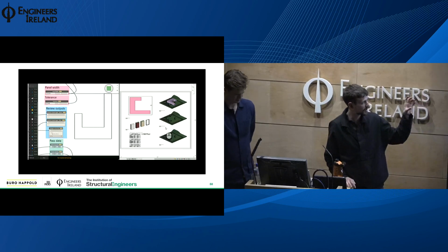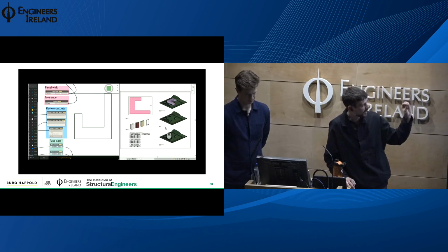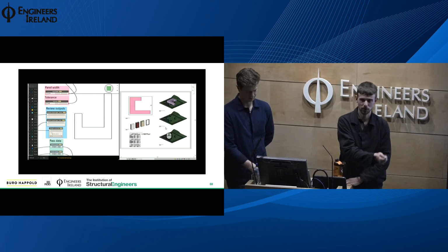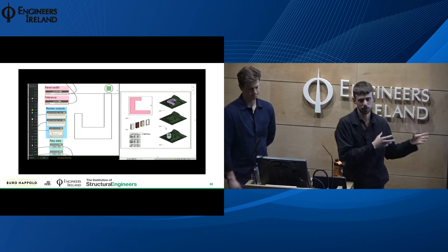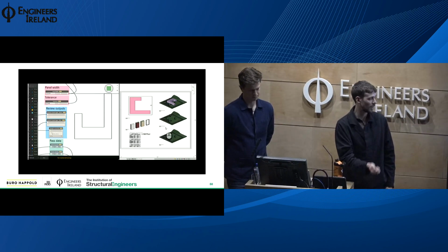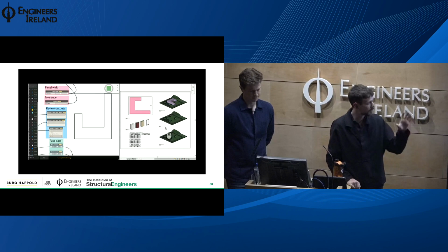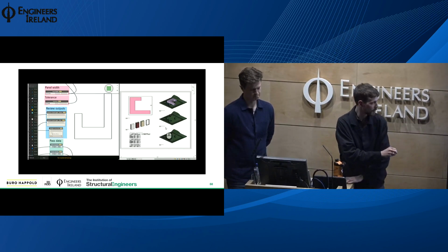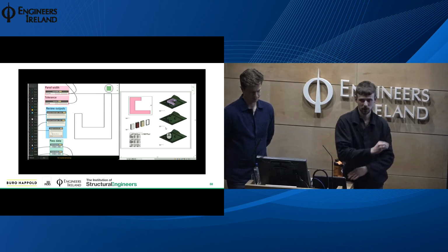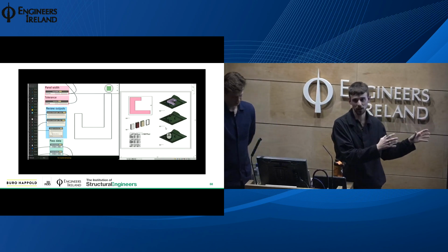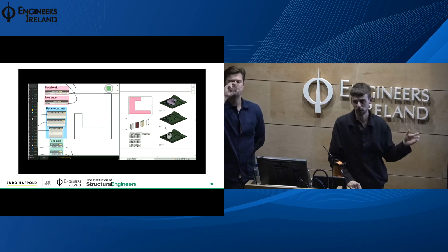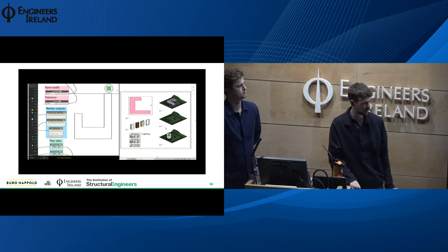So this is working towards embedding digital design with DFMA into an architectural model, so you have this library of ready-built modules and components which can be switched out for factory-made options. So, flying around the design and seeing the impacts on the floor plate, I put some window components in, and all of those have all of the manufacturing data embedded in. So you've got these stage 4 ready objects being loaded into a stage 2 job, so that when you're having to make these decisions earlier and lock in a manufacturing type or a construction type, the components work because you're building them off a resource of existing knowledge.